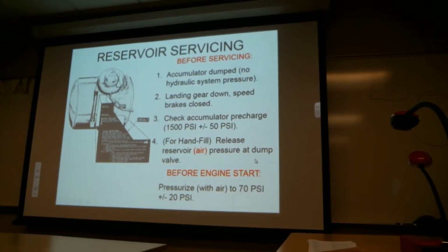So on that, it says on the accumulator dump, you still have a pre-charge? The pre-charge means the gas pressure that's in the accumulator. It's the initial push that is going to be available later on the fluid. But on the accumulator dump, you're dumping the fluid pressure, any pressure that's retained in it. But the pre-charge is a different thing. That's just the gas pressure. The other thing is exactly what's in the reservoir itself.